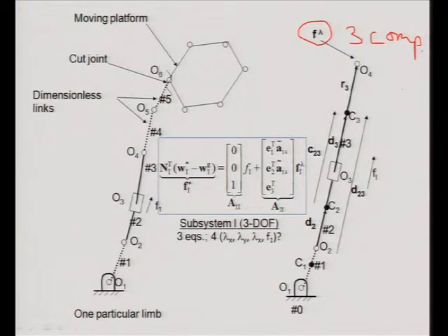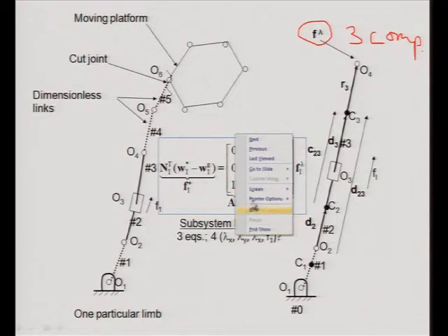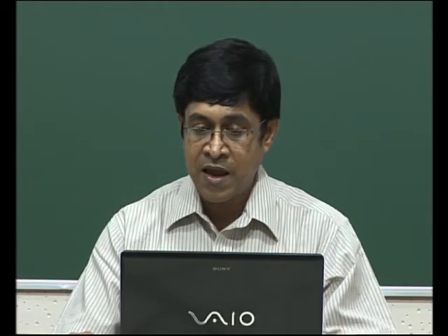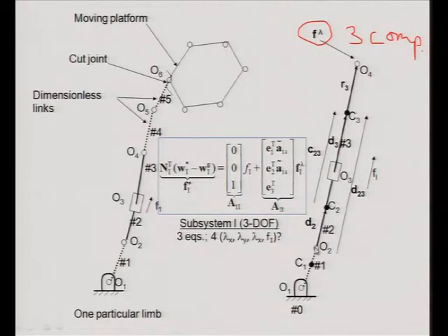Okay. And then at the bottom I have Hooke's joint. So, I separate them equivalent to 2 revolute joints intersecting at one point. I am showing by dotted line, these are kind of virtual links which have no mass, no link length actually, and they are substituted with 2 revolute joints, 1 here and 1 here. So, now I have 1, 2, 3, 3 degrees of freedom actually.